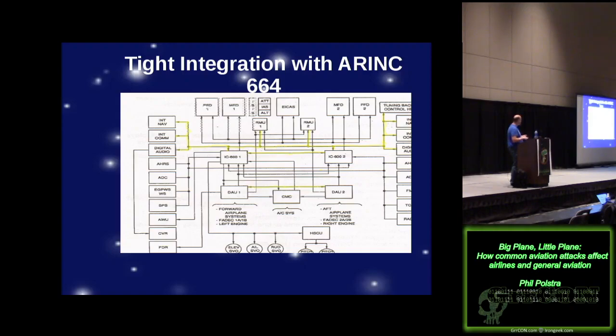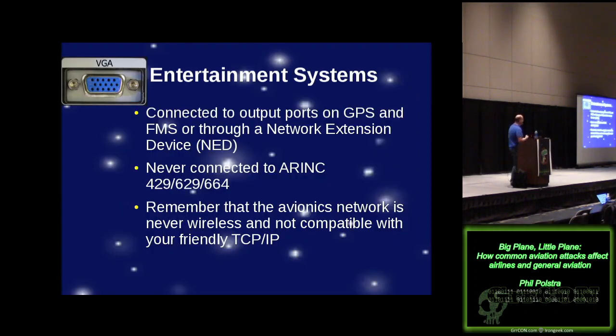Now, one thing I should say is this is a schematic, right? As a schematic, it's not going to show you certain components. And one of those components is a networking switch, right? So if you look at avionics switches, every single connection in there has to be programmed, right? So I have a connection from port 1 that maybe has some sort of a sensor on it, and port 2 that, let's say, is connected to my flight computer, right?